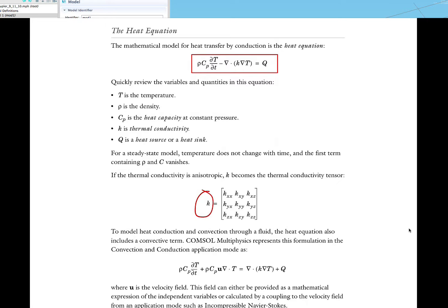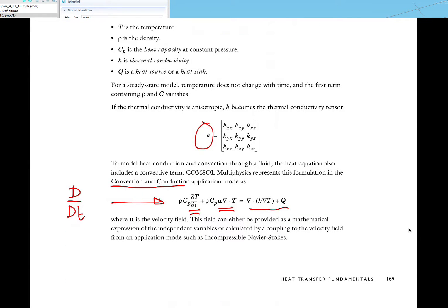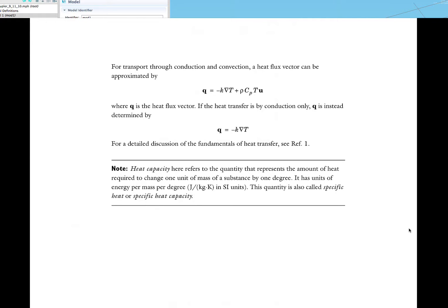where, if we have convection and conduction, notice that this equation here has only conduction. If we have conduction and convection, which is like in casting, then we would have the material derivative D/Dt that I talked about. So the material derivative gives you two terms, dT/dt, and then the convected quantity u times the gradient of the temperature. The right hand side remains the same as before. So these will be two variations, either the top one for conduction alone, or the bottom one for conduction and convection.